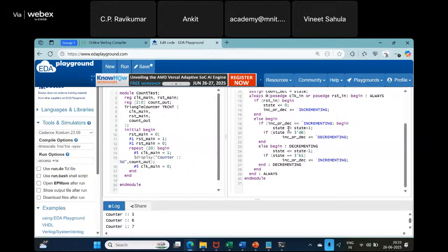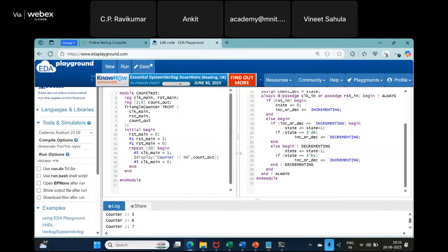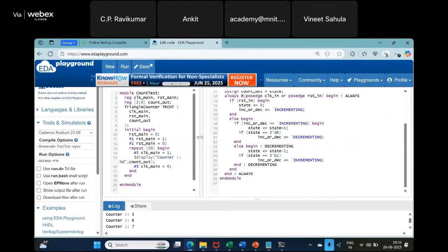So see, if it was a blocking assignment, 6 will become 7. And then I was okay if I was going to compare by 7. But because we are using non-blocking, immediately when we test, we should test it at 6. Okay, similarly here. So that was a subtle bug. Okay, so if you replace it with blocking, you will get 7. Let me try.